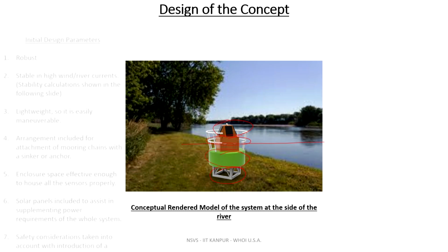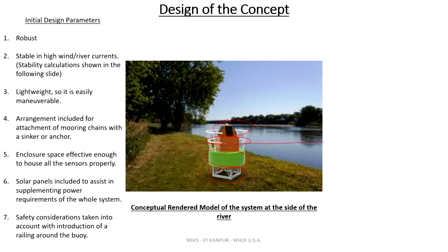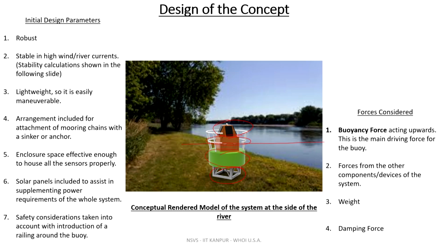So, that is the overall system that we had in our mind, and the design objectives were that it has to be a robust system, stable in high wind and river current, and lightweight, as I told you, with an arrangement included for attachment of mooring chains at the bottom, enclosure space effective enough to house all the sensors properly, solar panels, and safety considerations. For the buoyancy part, the forces that are considered are the buoyancy force, the force from other components or devices, weight and the damping force.